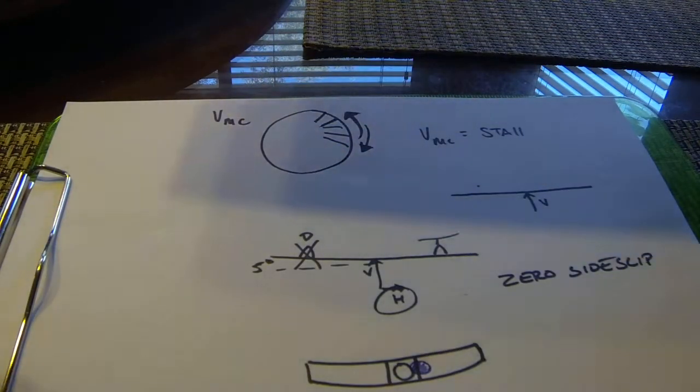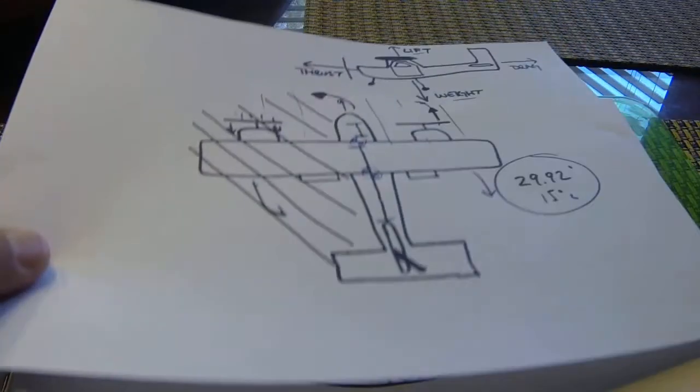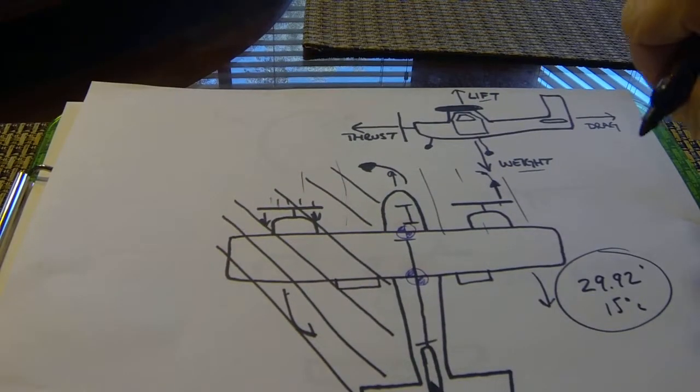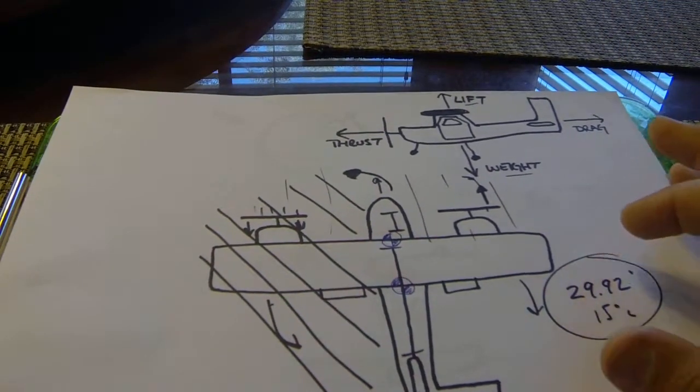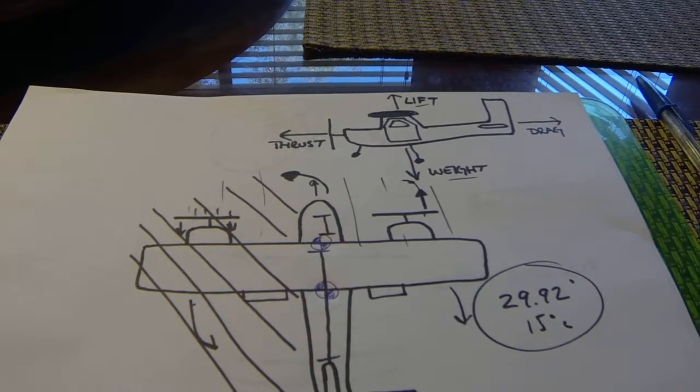Let me see if I forgot anything. I do not think so. Just some interesting facts, I guess you would say. Figures. I'm going to look at my notes here real quick. On this drag, we want to delay our descent, obviously, right? Some light twin aircraft are able to maintain level flight on one engine. Most are not. We talked about losing 80 to 90% of our performance.